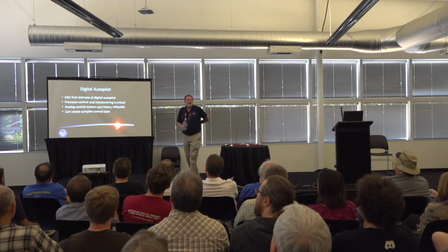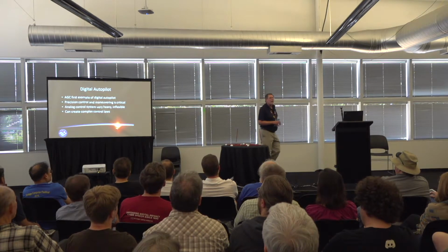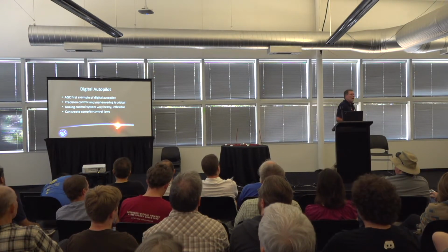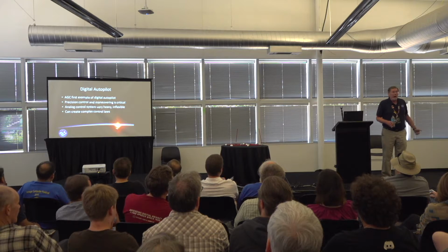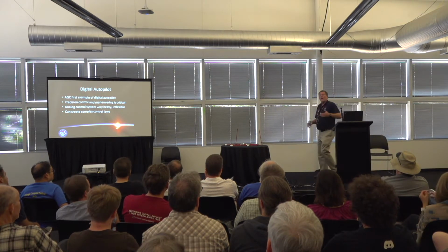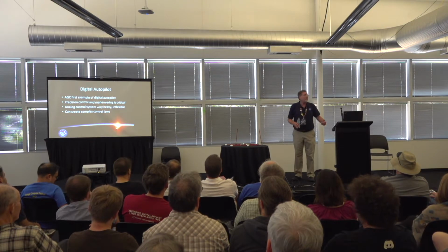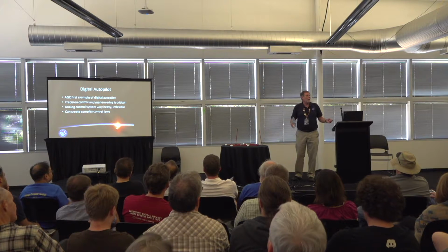You had to not only account for different mass properties. Think of what you have to do when you're flying an airplane or a spacecraft. Well, if I'm using thrusters, the little rocket engines, I need to know how long to fire them. That's a function of mass. If you have a rather lightweight spacecraft versus a heavy one, all those control laws change.